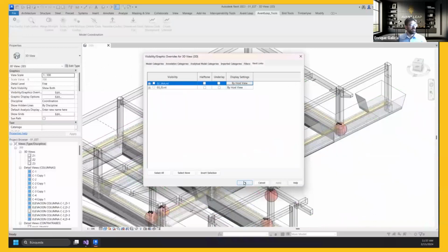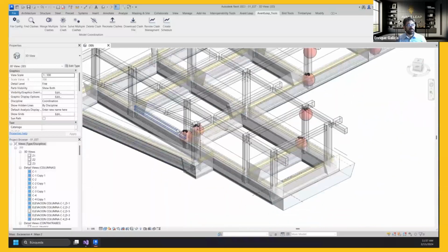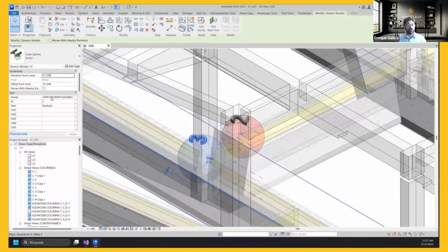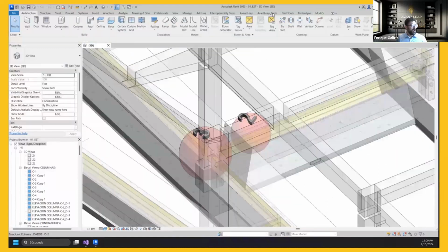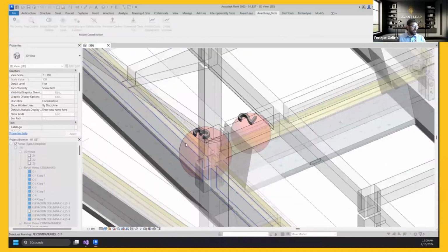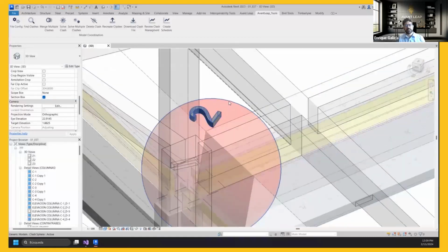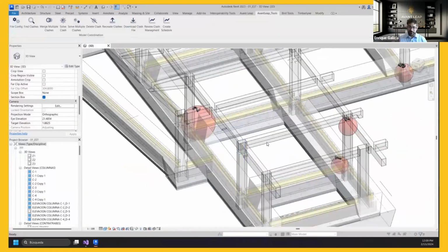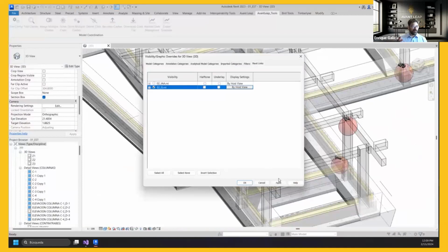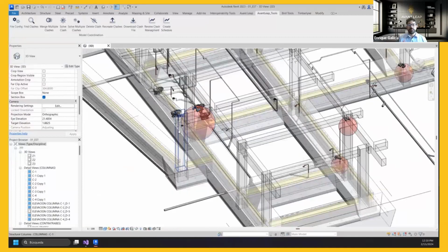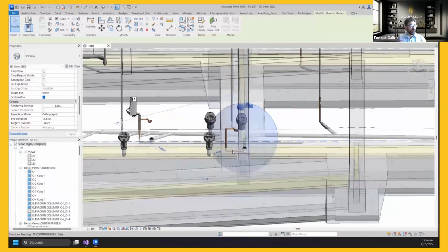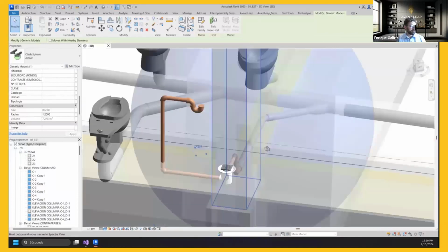But the good thing about this one is that within all those spheres, they have the information that they are requiring. They know specifically what the group is, where the elements that are colliding are, if they are multiple disciplines, or if they are within the size of whatever is getting intersected, and within the tools, they can get grouped. So in that case, we can set priorities for the objects, looking at Revit and fixing it if it's something fixable. If it's not, it can still be shared upon the CD environment, the common data environment, and grouped so that it will work with other elements.